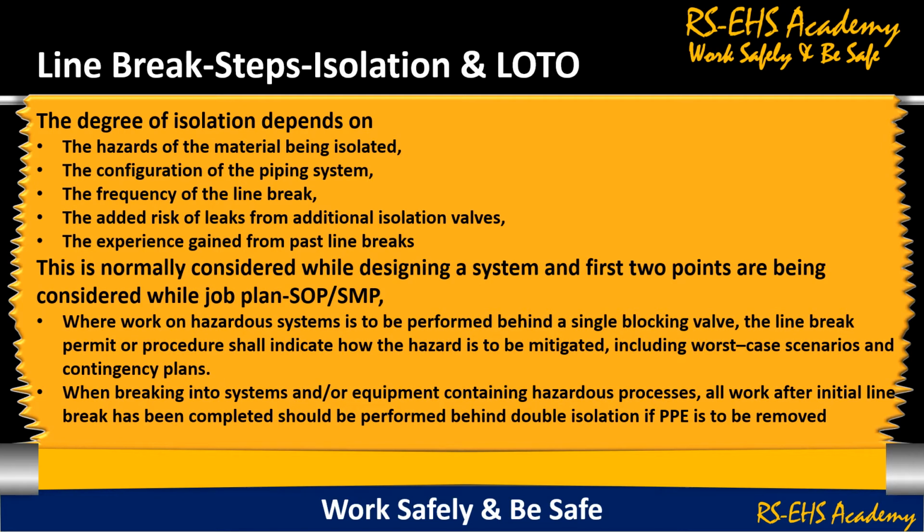Further to the line break step, isolation and LOTO, the degree of isolation depends on the hazards of the material being isolated, the configuration of the piping system, the frequency of the line break, the added risk of leaks from additional isolation valves, and the experience gained from past line breaks. This is normally considered while designing a system, and the first two points are considered while preparing the job plan, that is, SOP and SMP.